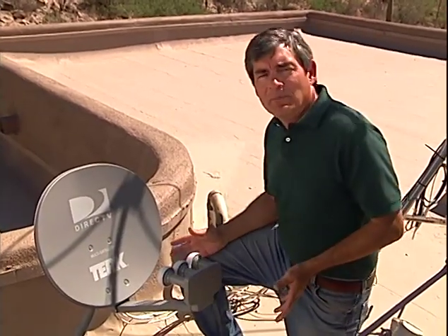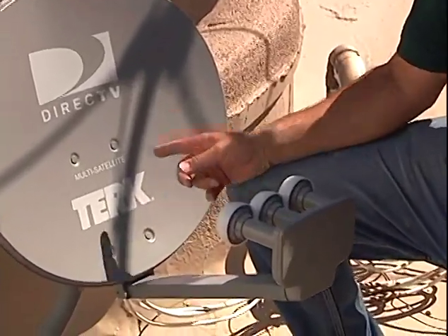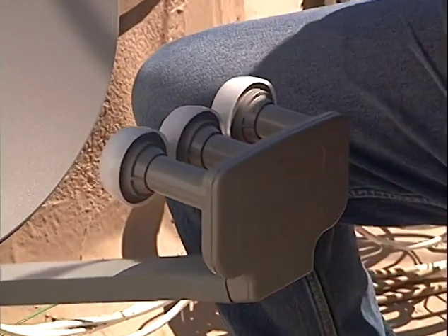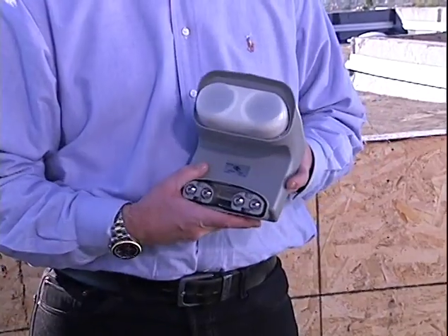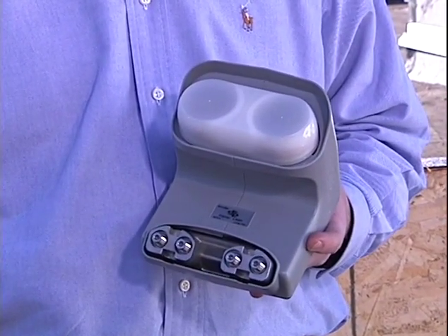Unfortunately, multi-switch and LNB designs are constantly evolving. Even the satellite and transponders change. So make sure and check that the LNB and multi-switch technologies you're using are compatible and recommended by the services you're using. Since multiple receiver installations are so popular, many manufacturers of multi-LNB dishes are building them with multi-switches built in. This 3 LNB DirecTV dish from Turk has a multi-switch built in which will support 4 receivers. This Dish Pro quad output dual LNB allows up to 4 Dish Pro compatible receivers to share the same LNBs.